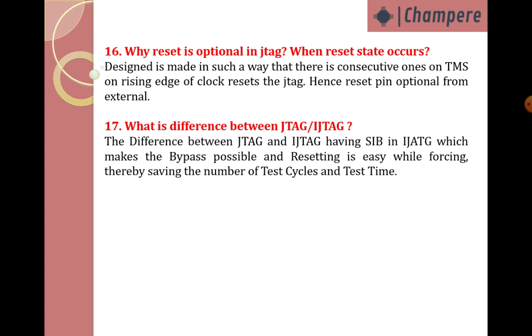The difference is that IJTAG has the SIB, segment insertion bit, which makes bypass possible and makes resetting easy while forcing, thereby saving the number of test cycles and test time. So this is one way IJTAG saves time.